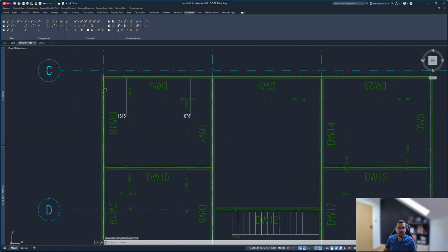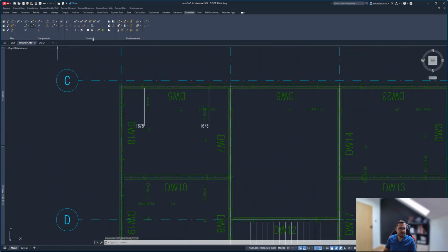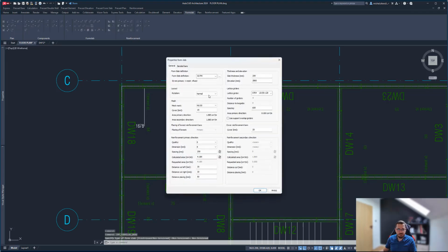With that, let's go ahead and actually place the slabs. So let's drag the slab like so. Here we get the initial placement options for the slabs. So we can select the type of slab. The first one that we used was just an error because some settings here changed by default. I had some different values set that are not compatible with this, but let's not worry about that. Let's go 3000 for the elevation of that, because I want to place my form slabs on top of my walls, and then we'll align the stairs along with that.